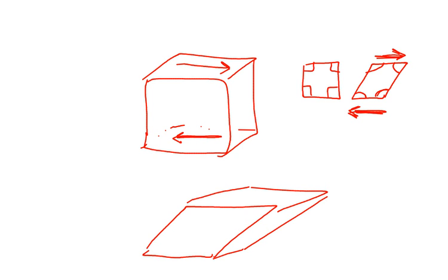If it simply elongates or shortens into a rectangle, then you have normal stresses. If it changes angle, then you have shear stresses. If it does both, then you've got a combination of both types of stresses. So that's what we're going to be looking at: these deformations that happen whenever we apply forces or stresses to our structures.